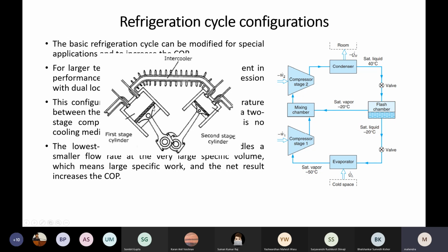Okay. So in that view, what are we doing over here? This we can call the low pressure cylinder. This we can call the high pressure cylinder. Here, from the atmospheric pressure to some 6 bar pressure, let us assume, we are compressing. Then that air, at 6 bar pressure and certain high temperature, is passing through this to the next cylinder. Meanwhile, what is happening? The pressure is constant because many fins are added over here. That heat is disposed to the environment.